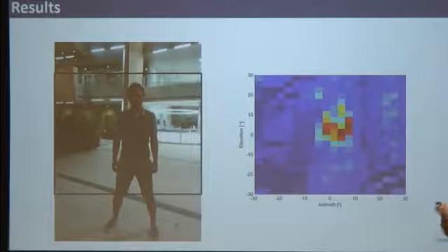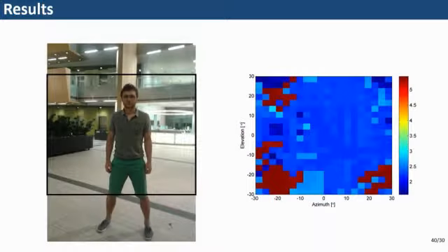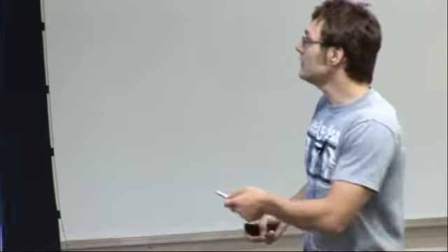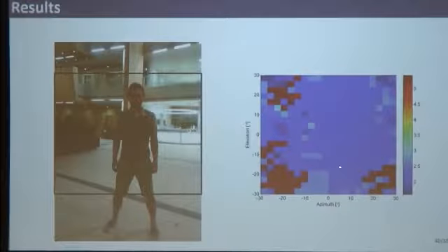A naive way to create a depth image is to just, as I said, point the beam there and measure the time delay. And I said this is not going to work because of the side lobes. And indeed, this is the depth image that you get with this naive approach. I'm showing this to you just for the drama, right? So you see everything is at 2 meters. Almost everything, because every time I'm standing there, some part of the side lobes will catch my body and create a reflection. So I'll think that everything is at 2 meters.